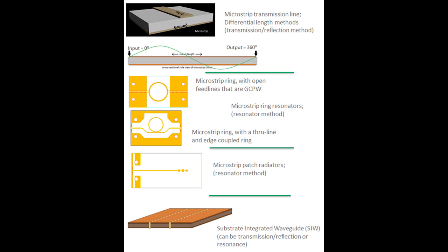So this has very small areas that the material is being sampled in, whereas the ring resonator has a larger area of the material being sampled for extracting the Dk. And then the transmission line is a long circuit, so it's sampling the material much, much more, and it's going to be more affected by the copper surface roughness because you are sampling the circuit much more and much longer.